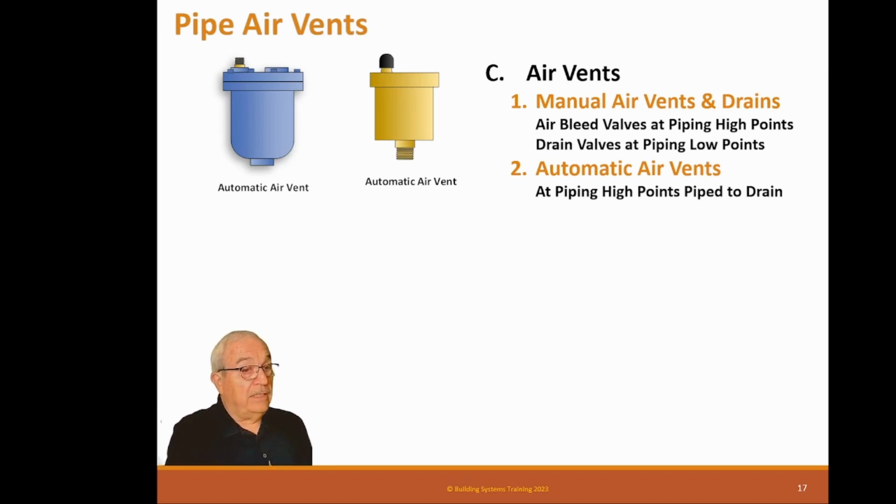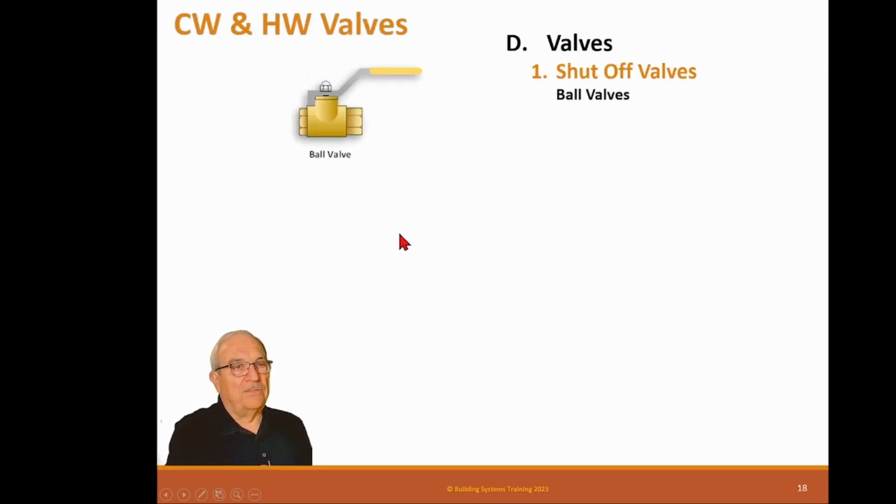And the only neat things about these, they work all the time, very important, but this needs to be piped to the drain. If you don't, people are going to get wet. It just spits out water every once in a while. So you have to make sure those are piped to the drain. Now valves, there's all kinds of valves.